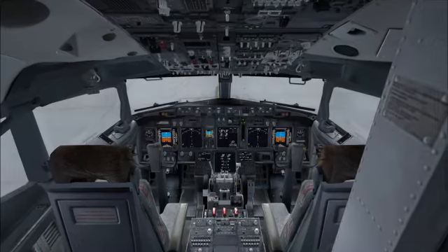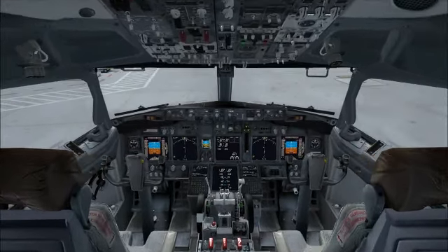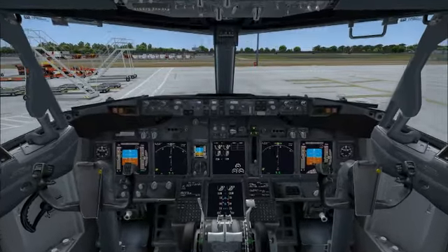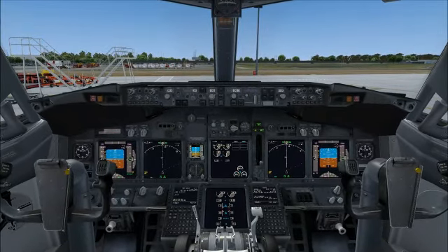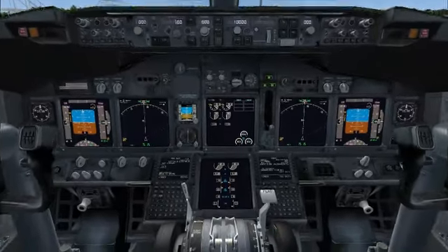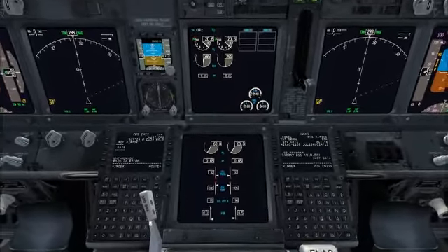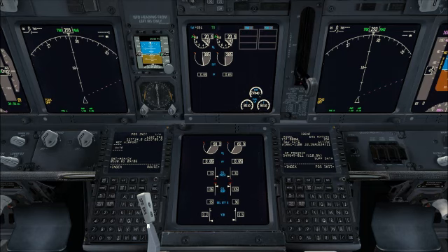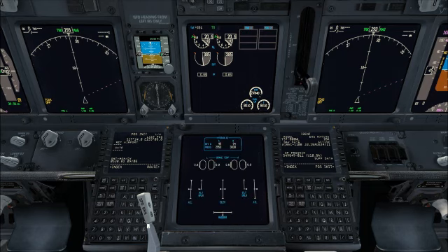The 737NG's Crew Alerting System consists of annunciator lights spread throughout the flight deck and centers around Master Caution and annunciator light panels on the glare shield. Unlike aircraft such as the 747-400 and the 777, the majority of alerts are not located on the upper or lower display units. These are reserved for engine indications and a small amount of other system information.